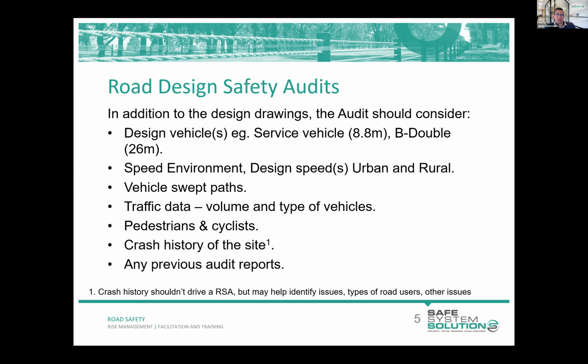Some of that information includes details of the design vehicle. Some of you, I'm sure, have heard that term. The design vehicle is the largest vehicle that's expected to use a piece of road on a regular basis. And that really does influence a lot of the geometric elements of a project.